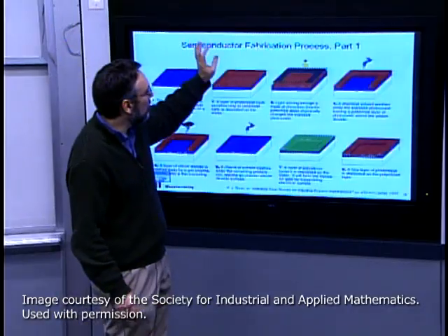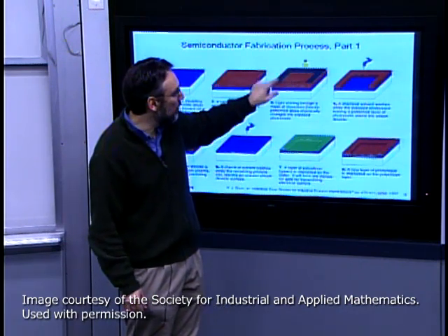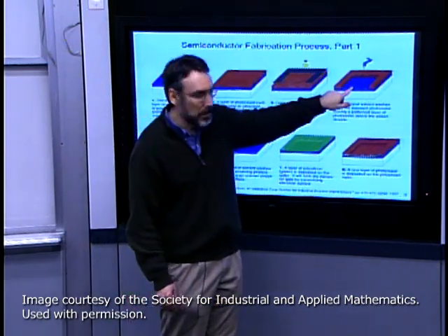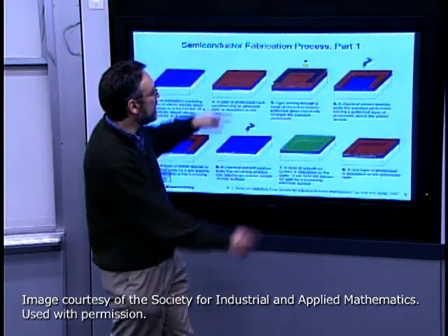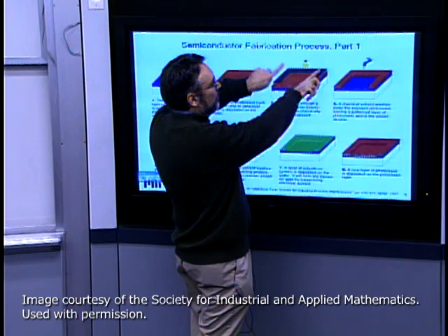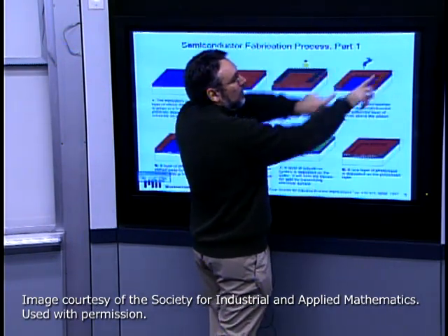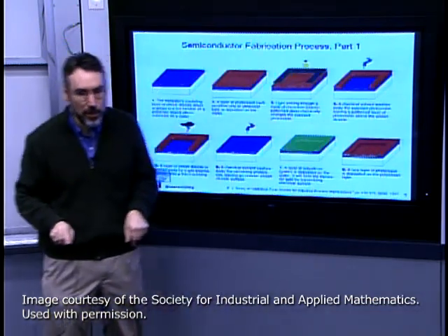So we have the spin-on resist, we do the exposure to light through the mask, then we do a develop, rinsing away the resist, and in the positive case, the pattern on the mask is transferred directly, if you will, into the pattern of the photoresist.